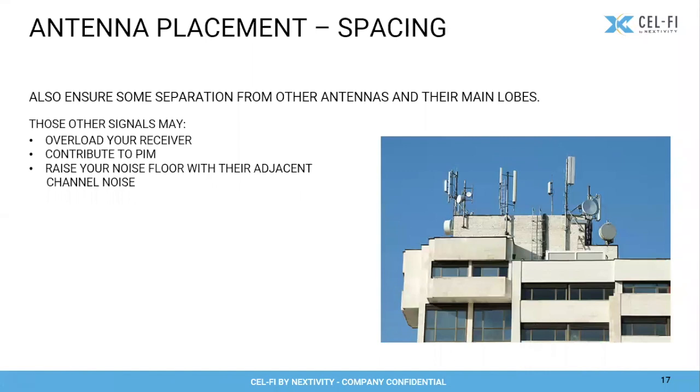These channels from transmitters are generally very well filtered with cavity filters a lot of times, but there will still be some phase noise, still some noise outside of their bands, which will increase the noise floor, because nothing's perfect. If they're anywhere near your frequency of operation, they could cause you a problem. So a little bit of distance is to your benefit.